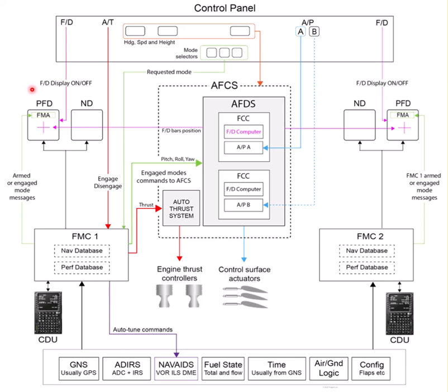So we've had the instruments, the pilot flying, the flight director coming in to help the pilot flying, and now we've got the autopilot. So now we can sort of relax a bit more because the autopilot is going to take a lot of the load off us. We still haven't brought in the auto thrust system, so let's do that now.